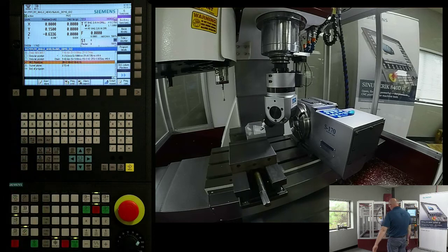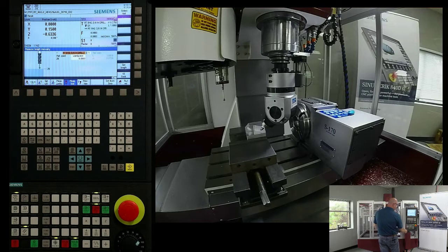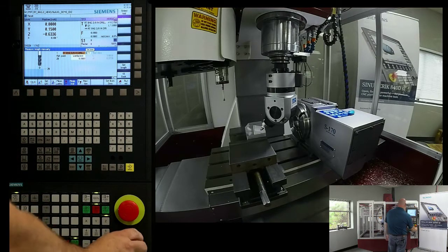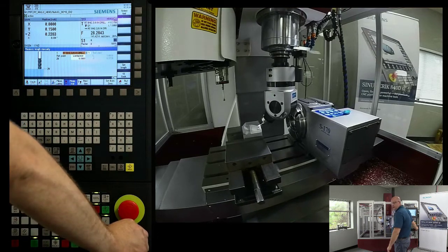Now what happens if, oops, I kill it, I shut it down? Well, that's okay. Depending on how I set up the parameters, the system will maintain that orientation angle. So right now, if you look at the control, it might be hard for you to see, but there's a little X and Z symbol telling me the coordinate system's rotated. Well, I can come back into my jog screen, and as long as I use this WCS mode and go to jog, I can now jog out of that hole, tracking that orientation angle.